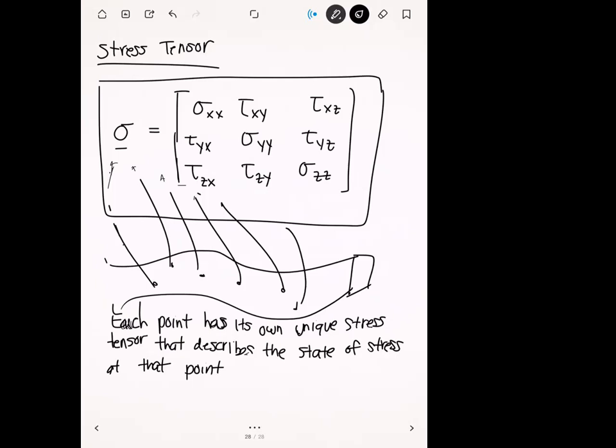But there's a bit of a disconnect here, because what I'm telling you is that stress is a complex state. Stress is not really a number, it's more of a tensor quantity. But what you're viewing in ANSYS is actually just a single number. You see a color contour plot, but the colors only represent a single value. The red would only represent a stress of something megapascal, it might be like 38 megapascal or something like that.